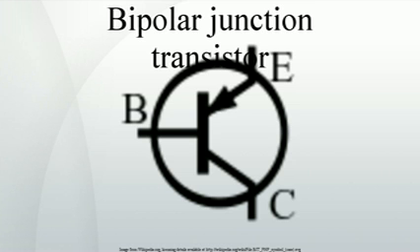That drift component of transport aids the normal diffusive transport, increasing the frequency response of the transistor by shortening the transit time across the base. Two commonly used HBTs are silicon germanium and aluminum gallium arsenide, though a wide variety of semiconductors may be used for the HBT structure. HBT structures are usually grown by epitaxy techniques like MOCVD and MBE.